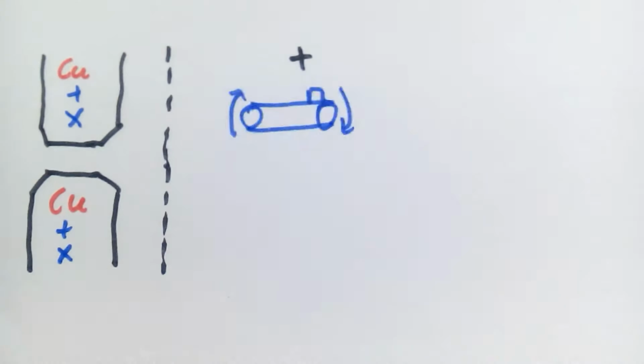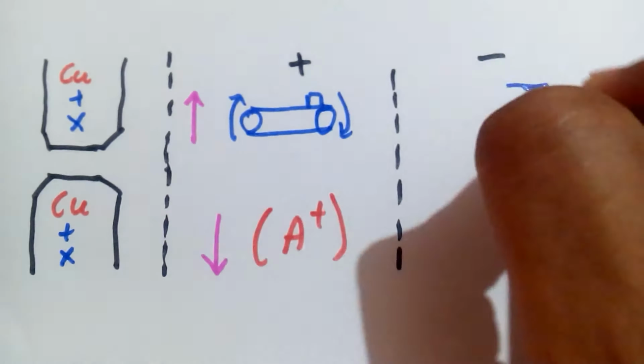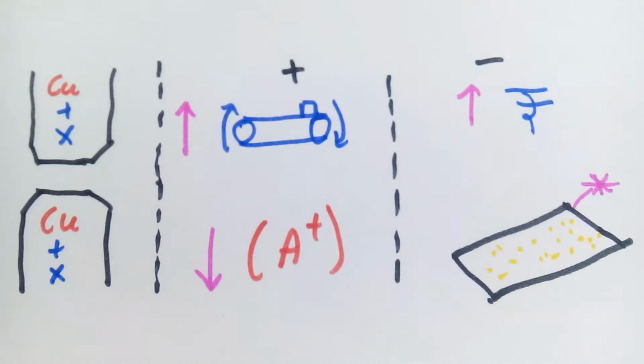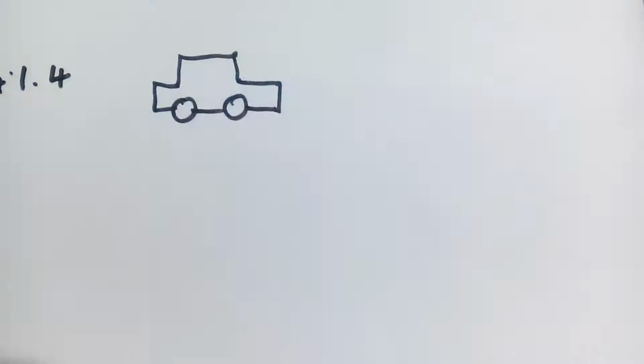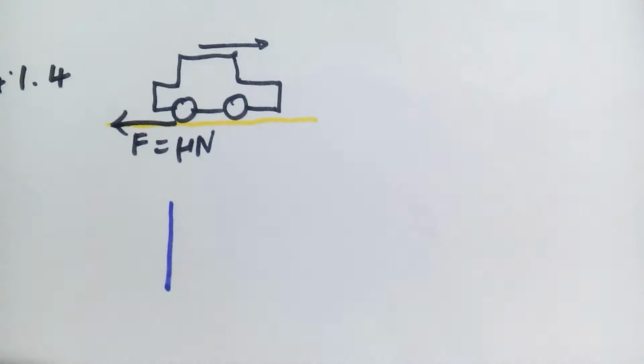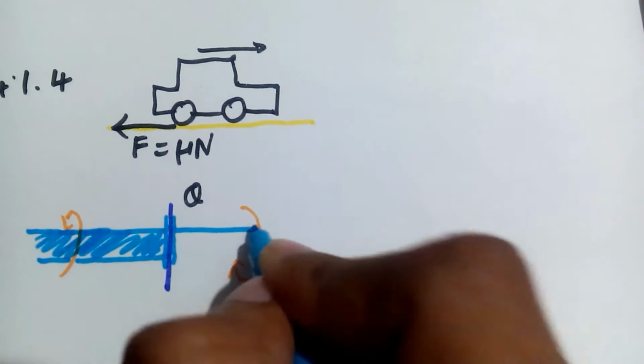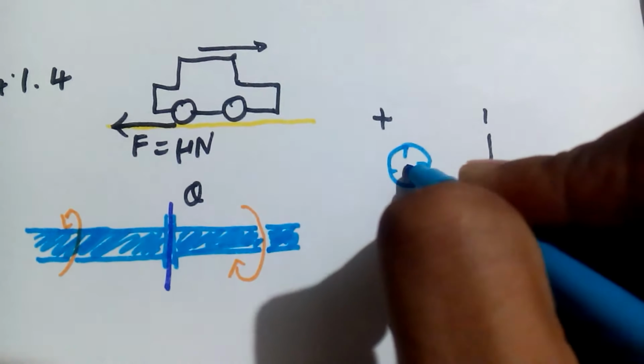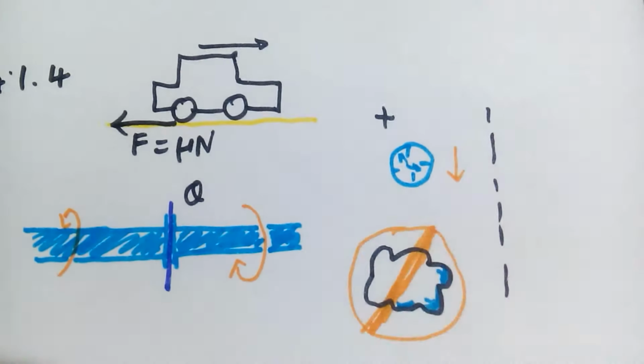The electrodes are mostly made up of copper alloys. Advantages include high rate of production and less skill requirement, but it is limited by high equipment cost and special surface preparation requirement. The fourth type of welding is solid state welding. Here, coalescence is produced by the heat obtained from mechanically induced sliding motion between rubbing surfaces. Advantages include single operation, less time requirement, and no smoke, with a limit on dimension of workpiece.